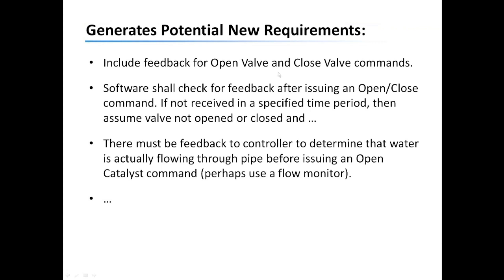We need to include feedback for the open and close valve commands. The software shall check for feedback, so we've got a new safety requirement for the software. It shall check for feedback after issuing an open-close command. If it is not received in a specified time period, then assume the valve wasn't opened or closed and do something. And that depends on your designers, what they want.